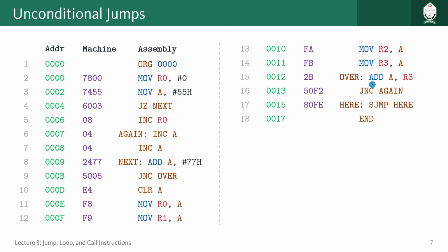So we will look at this one, jump if not carry again. Okay, and the previous two examples were jump in forward direction, this will be in reverse direction, right? Like here we have again, try to find out the relative address and also the current program counter value. So in this particular line, the current program counter value should be what?